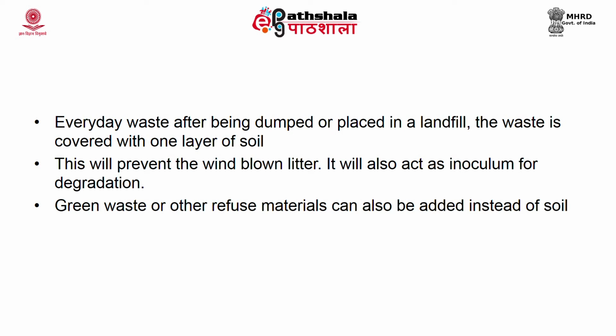Every day, the waste which is brought from the collection area is dumped, and once the day's deposition of waste is over, you have to cover that layer with one layer of soil. Now, this will prevent the wind blown litter. It will also act as an inoculum for degradation. The microorganisms present in the soil will enter into the waste and help in proper degradation.